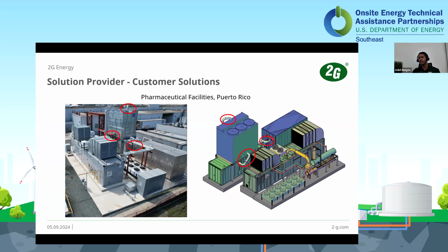And this site's been running for a year and a half, I think, at this point, closer to just a year. And this site we're doing cogeneration with a Sturgeon chiller. This is 1.4 megawatts of production with, I think, about 320 refrigerated tons of chilled water at 42 Fahrenheit. And I should mention, both this and the other units are on LNG for fuel.